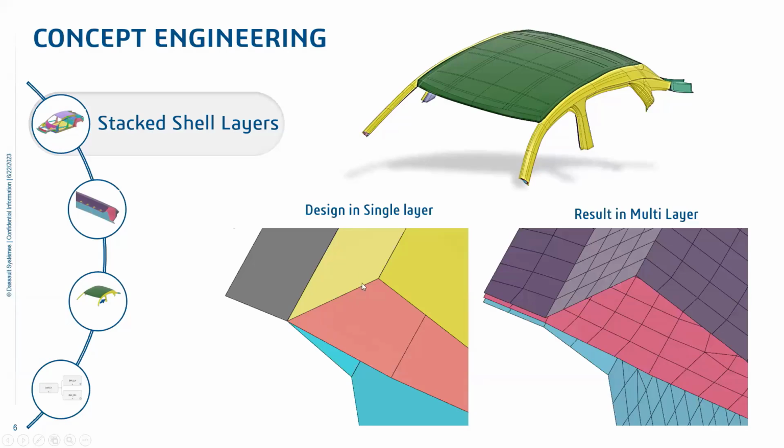So what you see on the bottom here is that, especially where you have this flange area where different layers, which are different sheet metal parts in reality, meet, the design by itself is set up in a way that those flange areas are always just one single layer or one single surface, which makes changes much easier, especially in areas where you have lots of layers meeting.